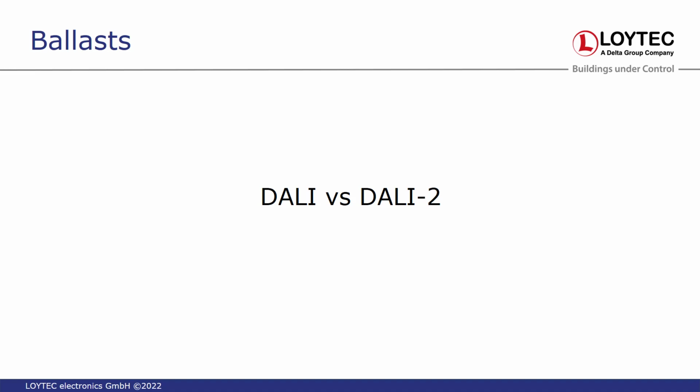And basically for DALI 1, everyone could say, I'm DALI certified, as long as you were a member at the DALI association. And as long as nobody proves that you are wrong, you can still claim this. It's similar to a CE mark. But with DALI 2, you're only allowed to have the DALI 2 logo when you pass this test, and you can look at the DiiA website to see what tests were performed and under what conditions. So in that case, you can be sure that it passed these tests.